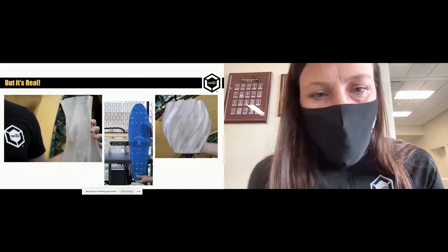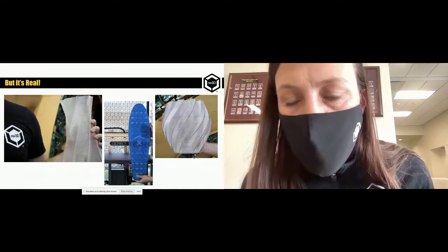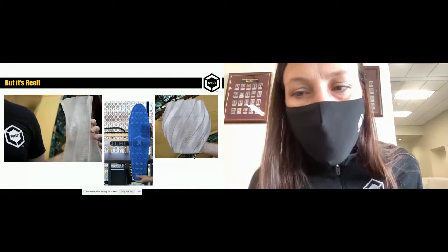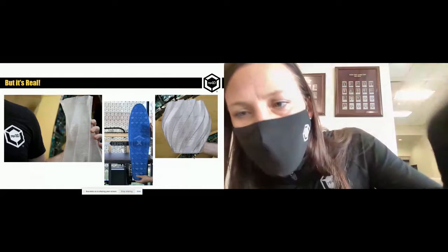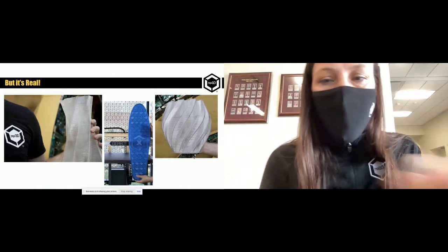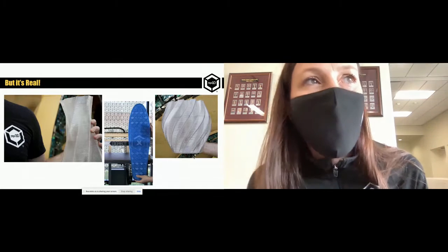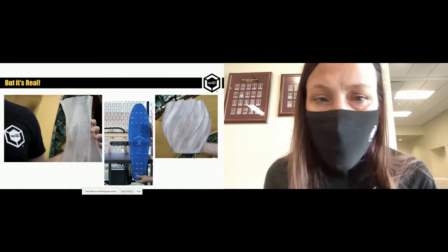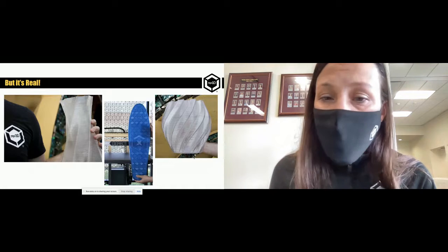And you'll also notice, just to point it out and to acknowledge what you see often in the industry, when you think of pellet printing or even pellet printing from waste, a lot of times you're going to see these parameter prints. That's because the pellet printers actually don't allow you to do retraction. So you do have to think about 3D printing in a new way. And there's a huge learning curve with that, but it is happening.